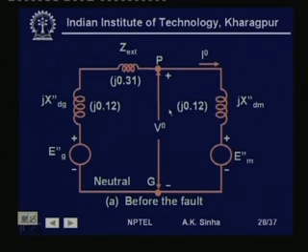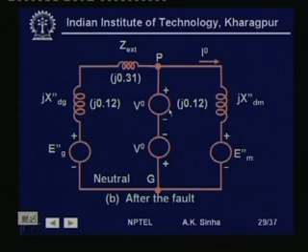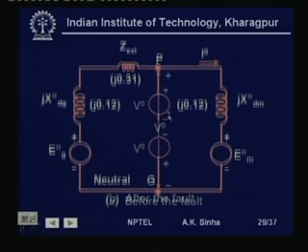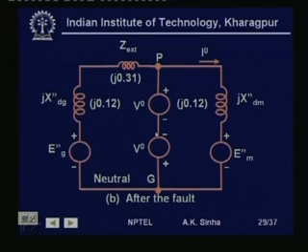Okay. So, now we can create a short circuit at this point by putting another voltage of the same magnitude, but with opposite polarity. That is, the voltage was V 0 at this point, which could be replaced by a voltage source here with V 0, with positive on this side and negative on the lower side. So, this is what we had earlier. Now, to create a short circuit, we have added a voltage with equal magnitude, but opposite polarity to this. Then what happens? The voltage between these 2 points becomes 0.